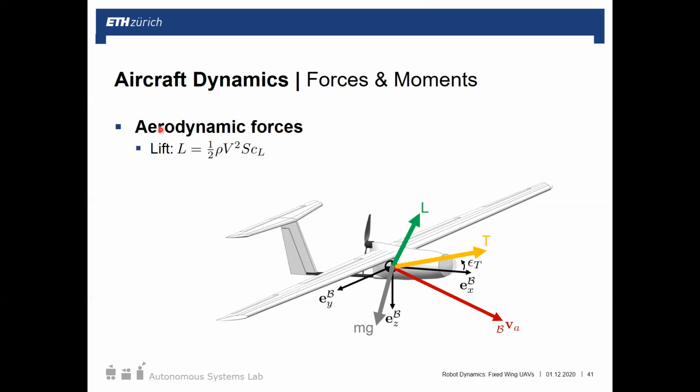This is a lumped lift equation summed at the CG, considering our whole wing, fully integrated, our fuselage lift, tail lift, everything summed into one about the CG. The surface area I'll get to in a second, but this lift coefficient again is a 3D version, so capital L. This lift coefficient is for the whole plane, the aircraft lift coefficient.